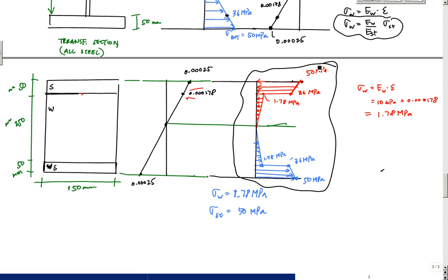Normally, you're not asked in problems to draw the strain profile, but drawing the strain profile is really useful, especially if you do any kind of experimentation, because most of the time, all you have to measure stuff are strain gauges and displacement transducers. And the strain gauges are used the most in terms of taking measurements off of a structure or a material. Okay, hopefully that was insightful.